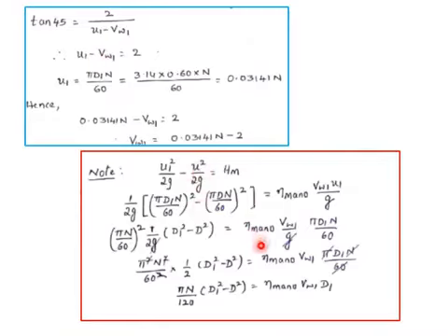That's what I said. If you don't want to remember that particular expression, then as usual you have to calculate this Vw1 from velocity triangles. Once you get this Vw1, then you can make use of this equation. But the only thing is, you don't substitute till then. You arrive at this particular equation and then you write this equation.